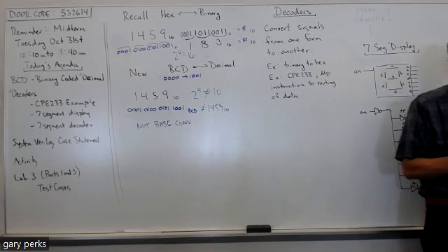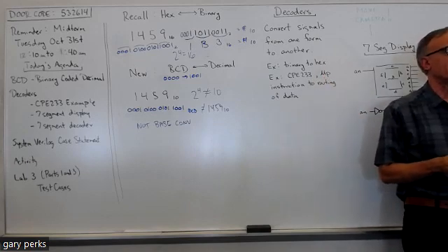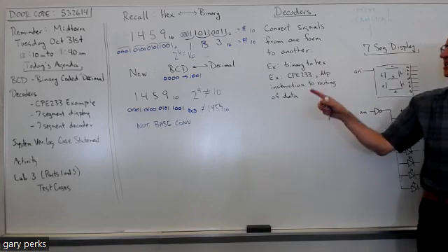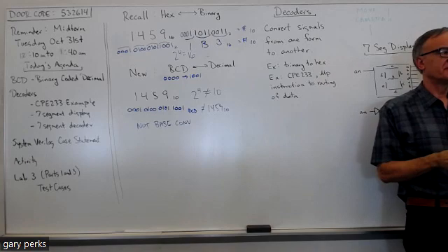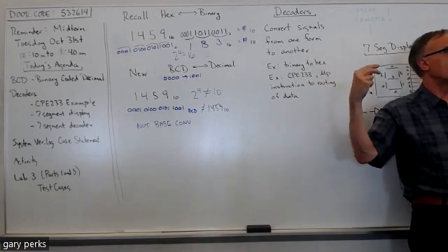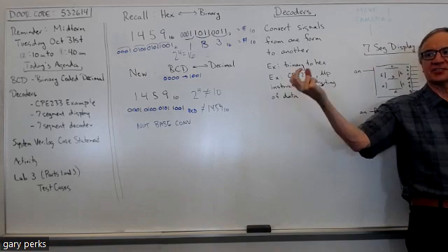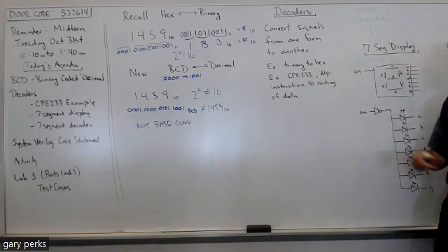One example of a decoder, and this is the one that's in lab 3 that you're going to design and build in Verilog, is binary to hex. You can have a decoder where you input binary and you output hex. Okay, so it's converting binary to hex in hardware.